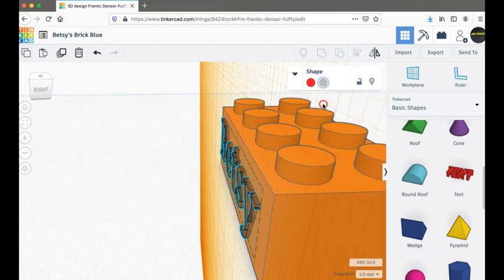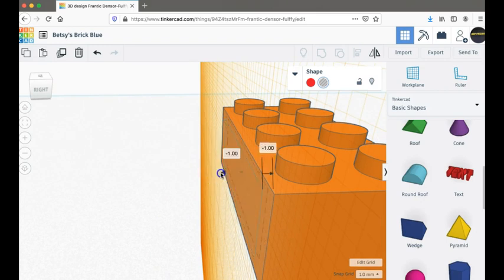So I'm going to go around to the side so I can see this. I call it a teardrop. It's also like a triangle. I'm going to click and drag it in 0.5 millimeter. Now you'll notice it didn't let me. It made me go -1. So I have a couple of options here. I can stop right here and quickly click on one of those buttons, one of those numbers, and change that to -0.5.